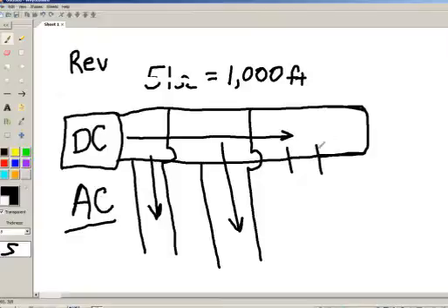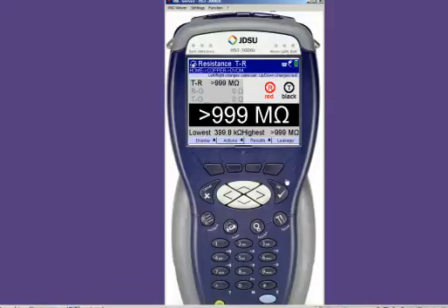All right, let's go back to the HST. Very important to understand, I believe, primarily because when I worked outside, I for a long time thought if the cable pair wasn't crossed, if it wasn't shorted or grounded, and if it wasn't open, I had a good cable pair. Well, nothing could be further from the truth. All you had was continuity between point A and point B. You hadn't done anything to check the quality of the pair's ability to transport AC signals. So back to our innocent old ohmmeter.